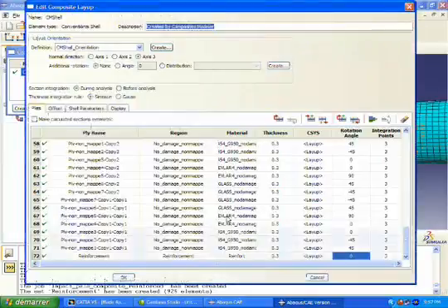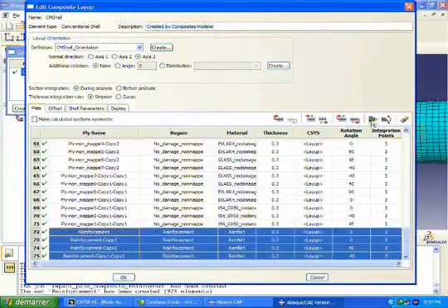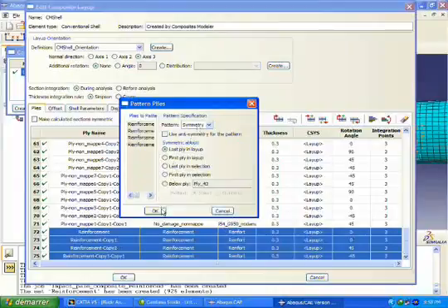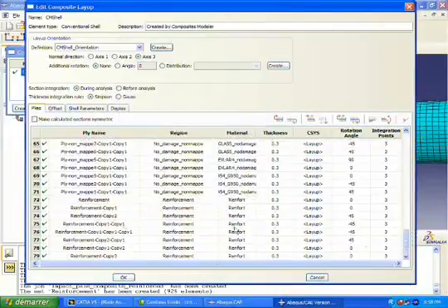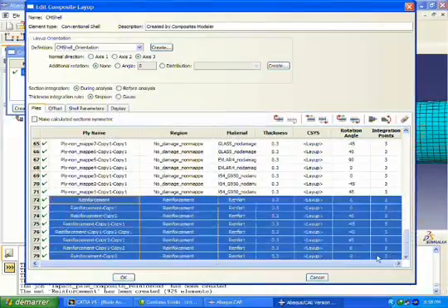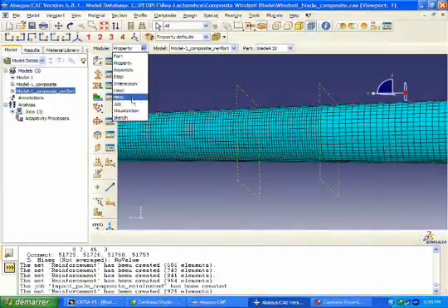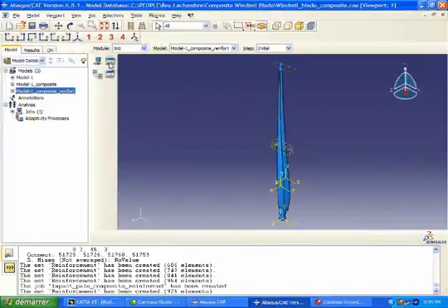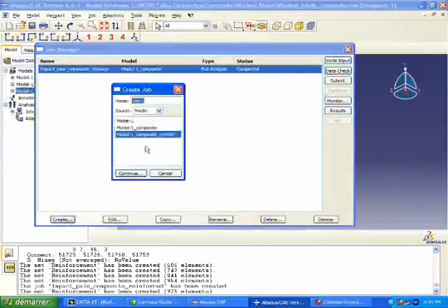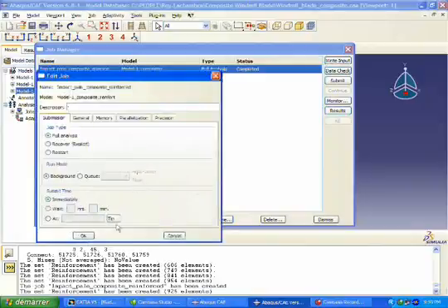So once we have that defined, we can copy. We're actually doing a symmetric layup copy. So now instead of just a single ply of reinforcement, we now have 8 plies of reinforcement there. So we're going to go back to our simulation job, create a new one called impact reinforced, and we're going to go ahead and submit this simulation.